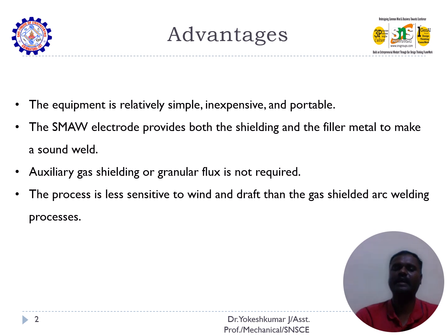Why do we have to use shielding gases or granular flux? Because during the welding process, the metal is melted to its molten state and it is in contact with atmospheric air, which contains oxygen. If the metal reacts with oxygen, it becomes metal oxide, which is inert in nature and degrades the material property.